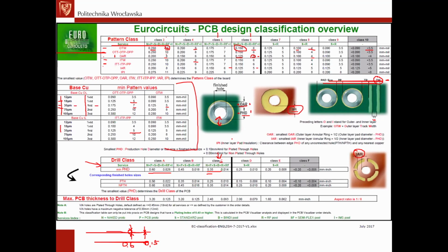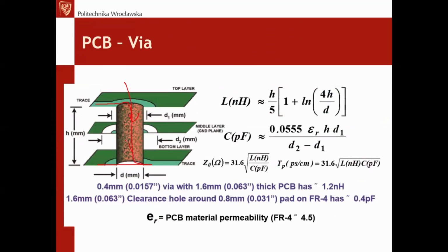Believe me, it's very expensive when the cracks appear. The problem is, from my years-long experience, that sometimes the cracks on the vias appear months or years after manufacturing. The broken via means replacement of the whole PCB. It's unfixable, because tracing where the via is broken is extremely difficult. You usually have hundreds of vias on the PCB.